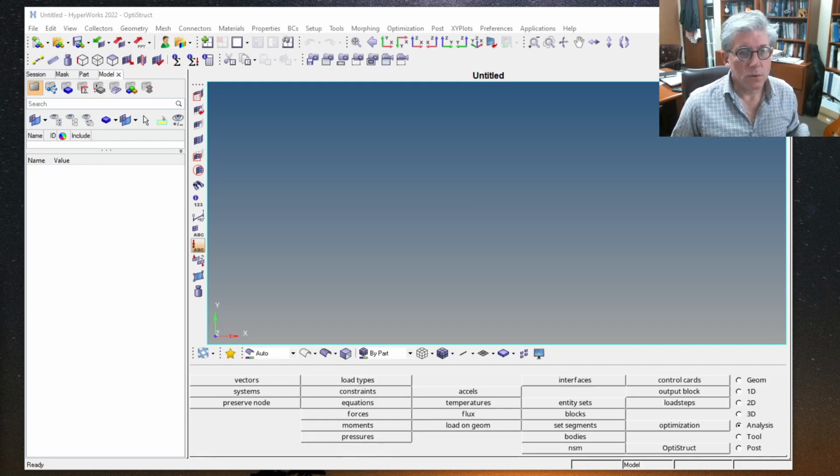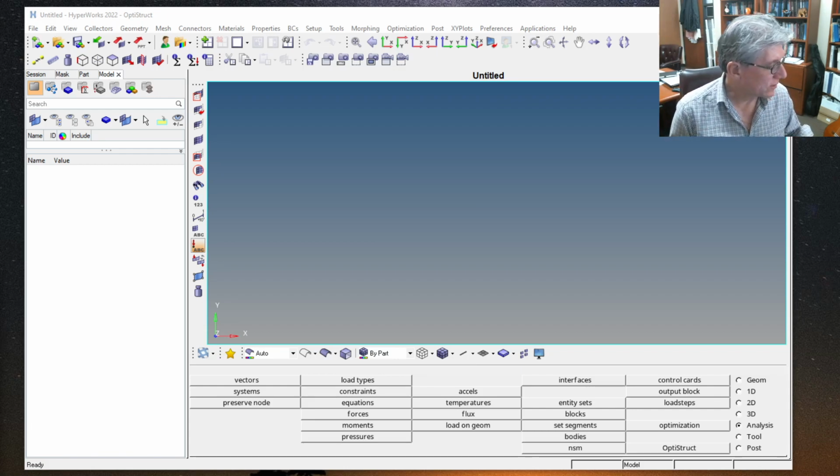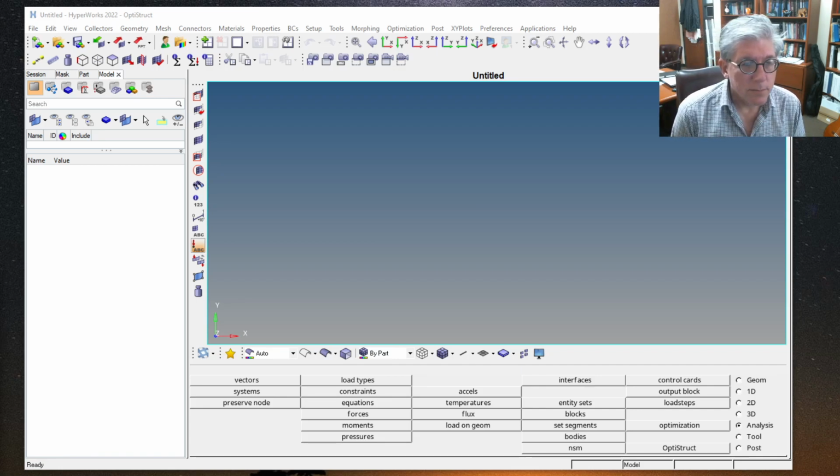Okay, so this will be the first finite element thing we do in this class. What we'll do is a really simple model using C-rod elements, which are basically like truss elements. They don't support any bending moment, just axial loads. And we will use this to solve that wing strut problem we did in class on Thursday.